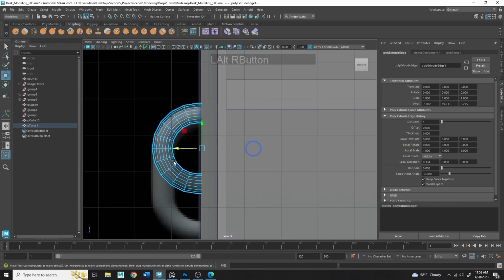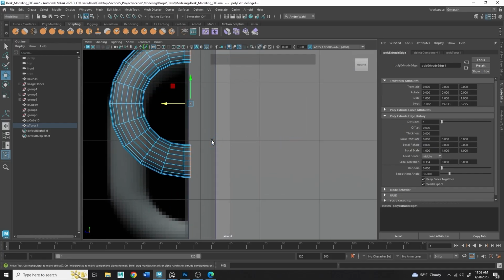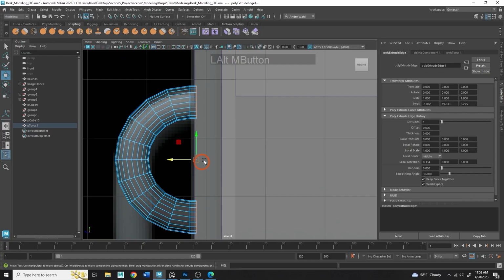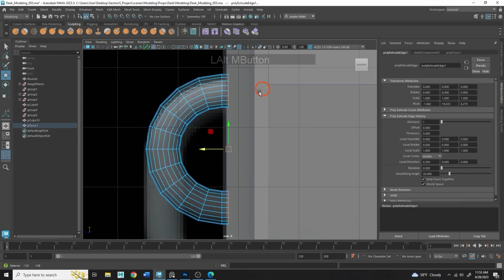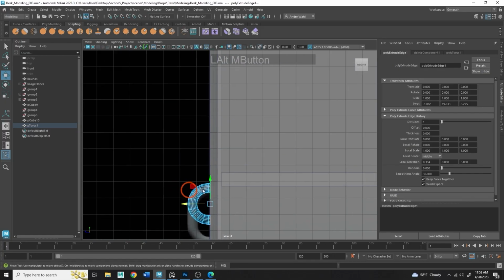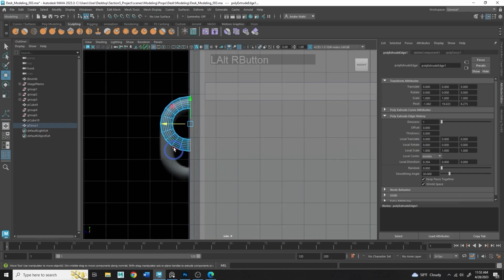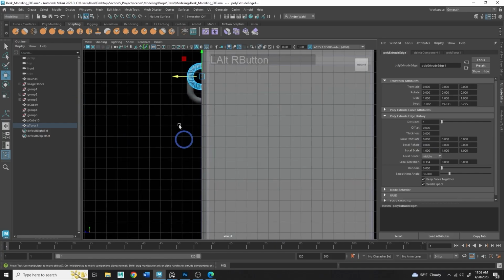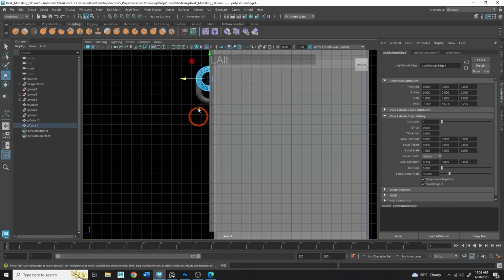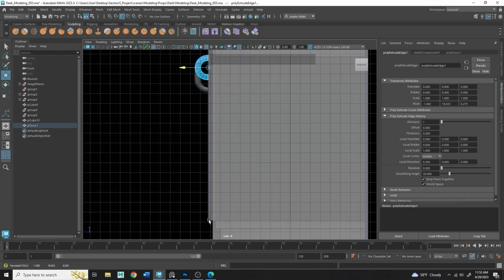It's actually okay if we don't do that here, though. If they go a little bit into the cupboard, it's not going to hurt anything. But if you did want to have it perfectly onto the cupboard, you could. Sometimes it does help with texturing and lighting later on. Since this is a background element, I probably won't worry, but the modeler inside of me makes me have to worry. So I'm just going to hold V, snap to vertex to match that to the cupboard corner down here.